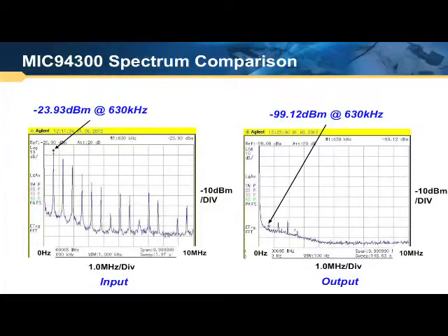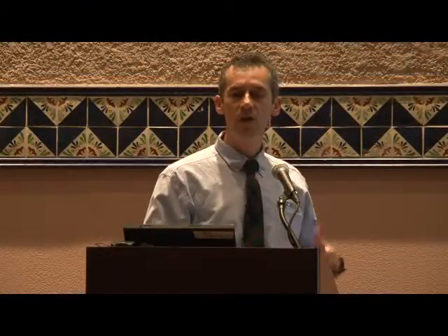So the capacitor sits on this output, and then the GM and the C produce an output filtering action. So your flat band suppression actually improves, and that will continue improving up until the parasitic ESL of the output capacitor starts to resonate with the capacitance, and then your PSR will start degrading again.